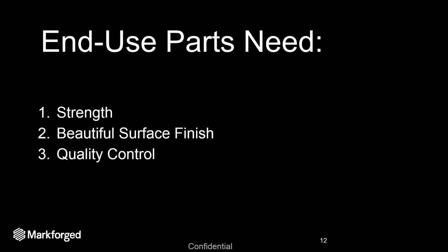How they do this is they first put down nylon as a base layer, about 4 layers of nylon. Then they put down some fiber. And when I say carbon fiber, it can be carbon fiber, Kevlar, fiberglass, or high temperature, high strength fiberglass, and it intersperses it with nylon.